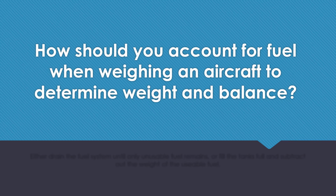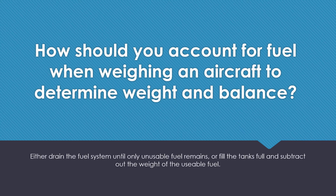How should you account for fuel when weighing an aircraft to determine weight and balance? Either drain the fuel system until only unusable fuel remains, or fill the tanks full and subtract out the weight of the usable fuel.